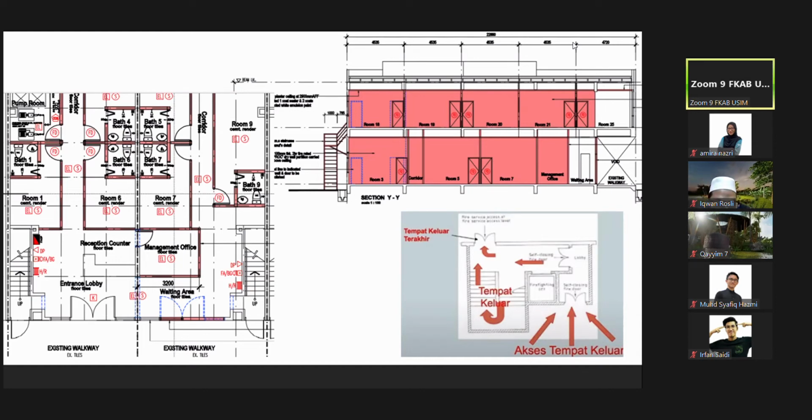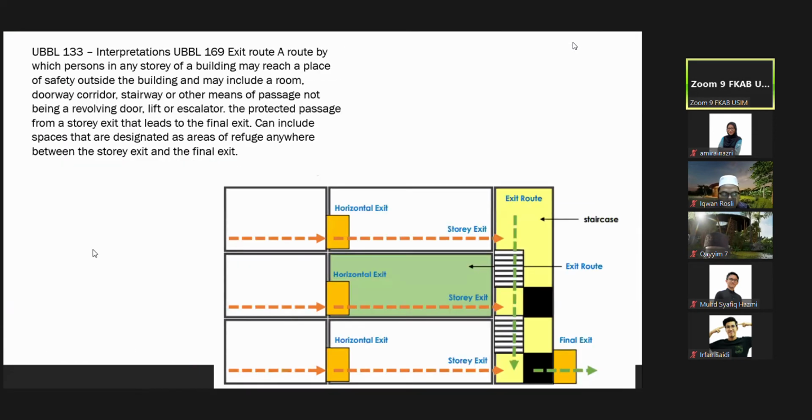According to travel distance. So look at the door here. When you are at upper level, you have to design the fire staircase and the fire door directly to outside. Directly to outside. Okay. Refer to the door here. Okay. So this is what is happening to the building that is more than 1 story. Let's say the 3-story here. So this is inclusive that all the fire staircase is inside one building.